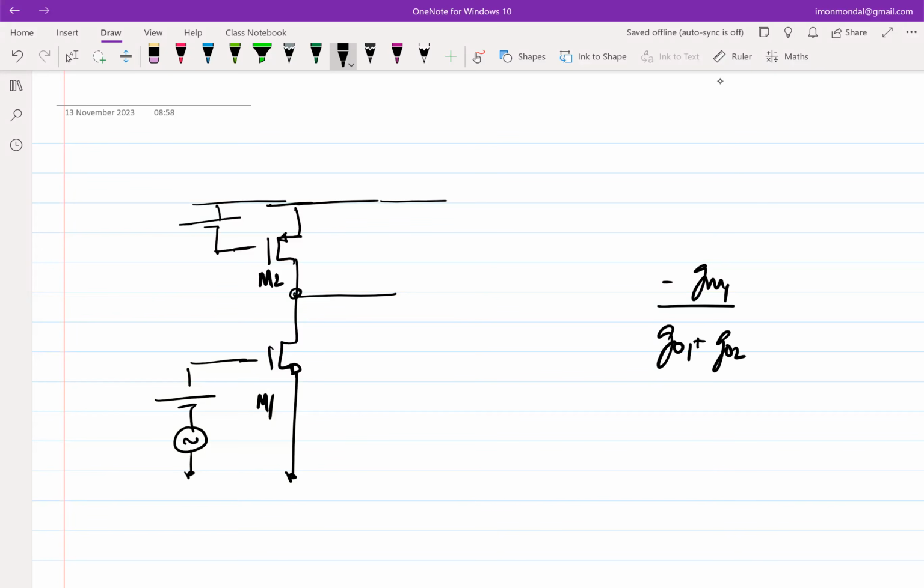Now, if I have to increase the gain, we know a few tricks, right? We can increase the W and the L simultaneously. By the way, in this case, let's say I keep W by L same, okay? And I want to bias it with a constant current source. There are multiple ways of biasing using a constant current source. So let's say this is the structure that I chose. Now I want to increase the gain by only changing I0.